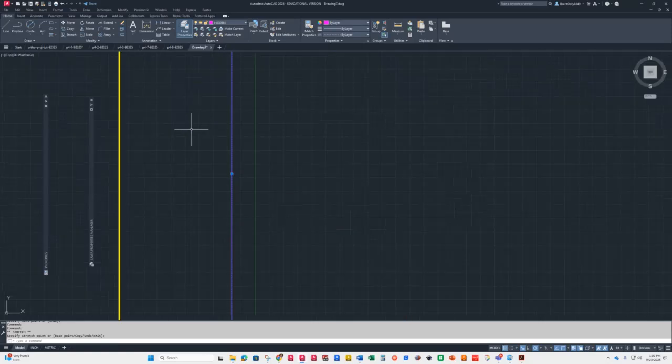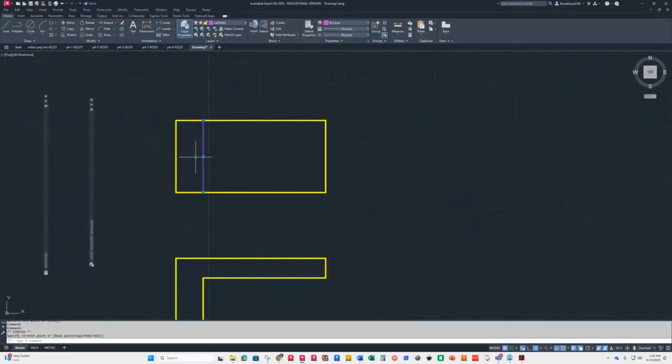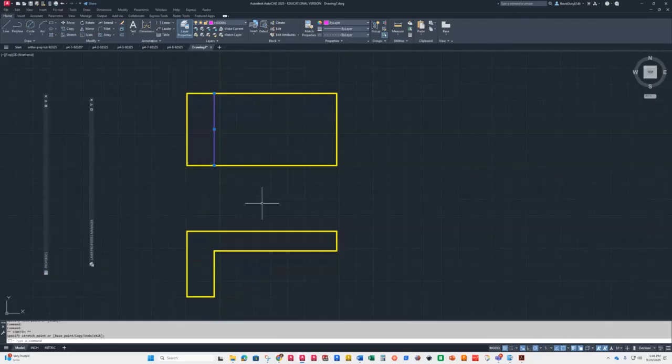All right, so looks like I got really tiny lines here. Wow. So how do we fix that? Well, it's actually pretty easy. LTS, which is line type scale. And like I said, metric line type scale is going to be larger than 1. How much bigger? Well, you don't want it to be 25.4, which is the actual equivalency between inch and metric, right? That's your scale factor.